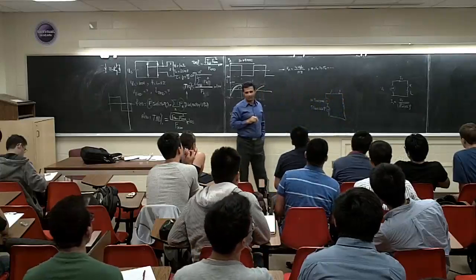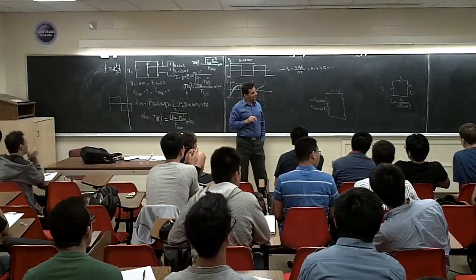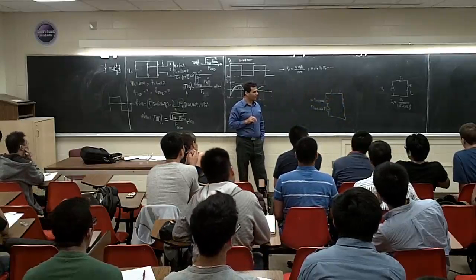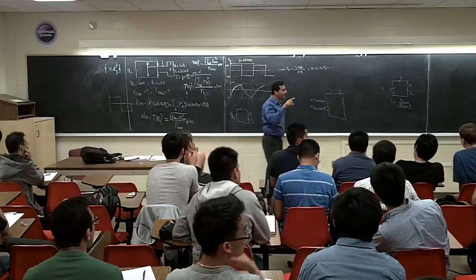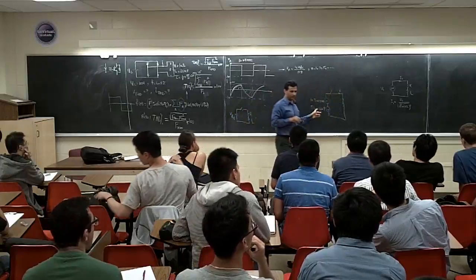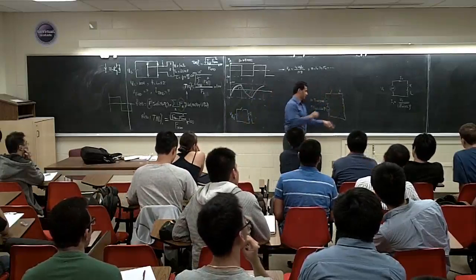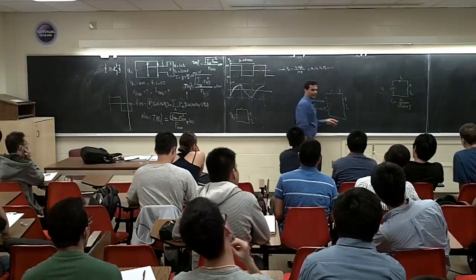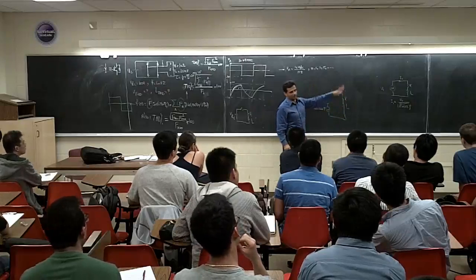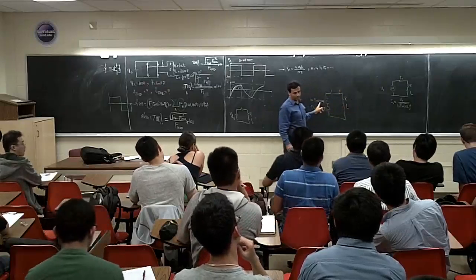Yeah. How? Just use the frequency and the amplitude of each source. That's right. So they call it the superposition theorem. Let's get rid of this one. I know how much the current is: it's going to be R and L, and I is going to be this voltage divided by that impedance at this frequency.